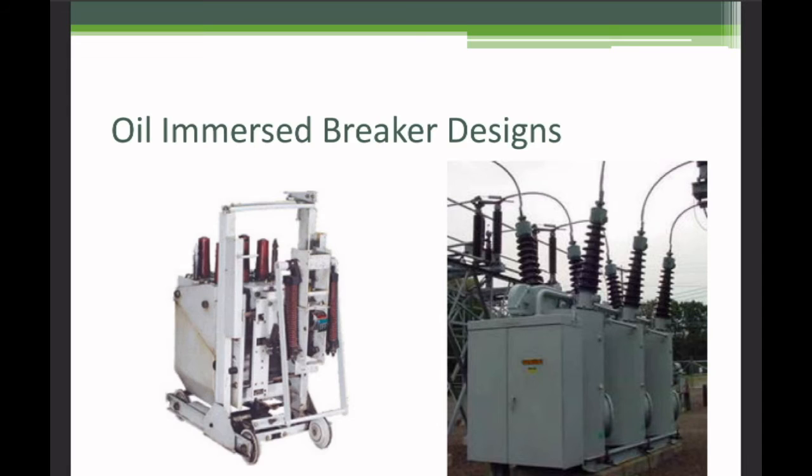Of course, if you get into some of the stuff that's really, really vintage, the arms that hold the contacts can actually be made out of wood, which becomes one more, laminated pieces of hardwood. So one more thing to keep an eye on during maintenance is that wood holding up, because it certainly doesn't have the same properties that some of our modern materials would.